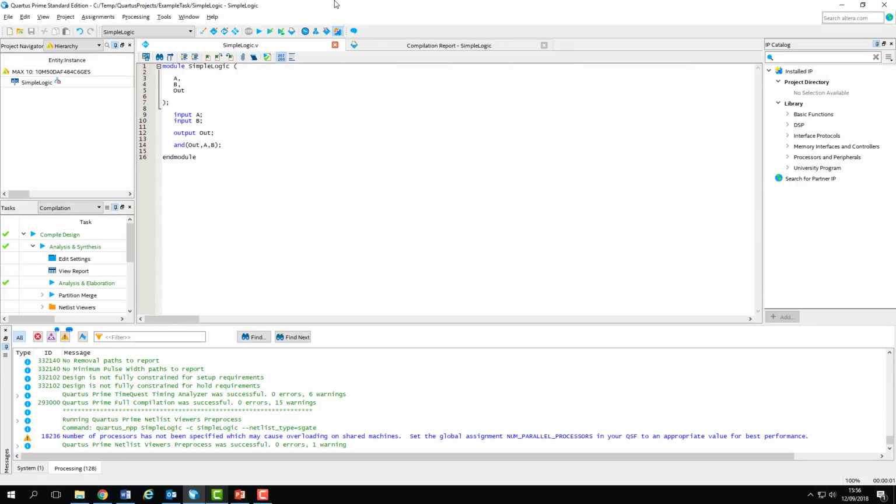So we're going to use Quartus' RTL Viewer to look at the RTL for our design. As I mentioned in the previous screencast, the analysis and elaboration stage of compilation determines the logic of your design by testing each module with all possible combinations of inputs and generates a netlist of gates which represent that module. By using the RTL Viewer, we can view this netlist as a digital circuit, so you need to make sure that at least the analysis and elaboration stage of compilation has taken place and has a tick next to it in the task window before you open the viewer.